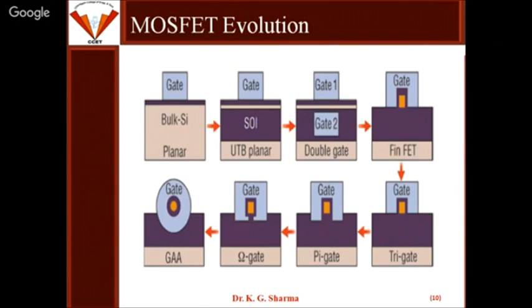So I on current basically changes in the same proportion with the drain voltage, but I off current changes more. Suppose we have increased the drain voltage 100 times, the I on current changes 100 times, but I off current maybe changes by more than 100 times, and that I off current is basically creating the change in the threshold voltage. Also it is changing the I off current, so more leakage current will be there.